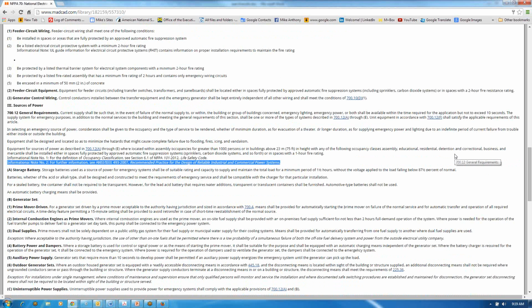So the issue of common cause failure has to be considered also. And unfortunately, it's a case-by-case analysis, but those are a couple of issues which I could provide as guidance for anyone facing the question of will a second utility feed produce any improvement in the reliability of my electrical supply, and quantify how big that improvement is or is not.